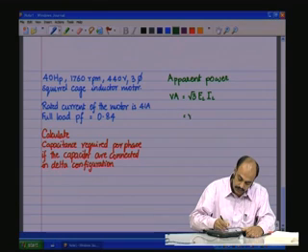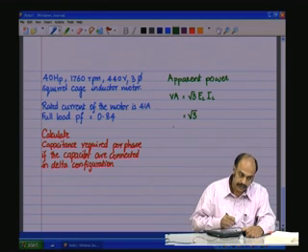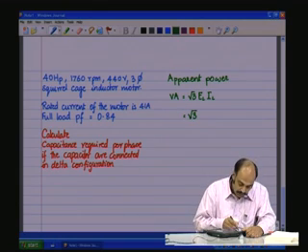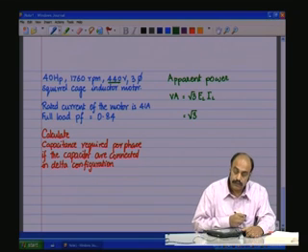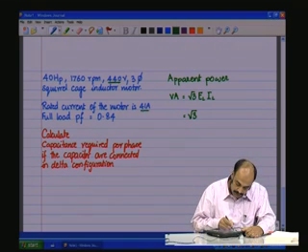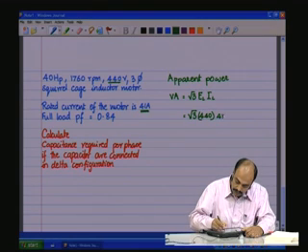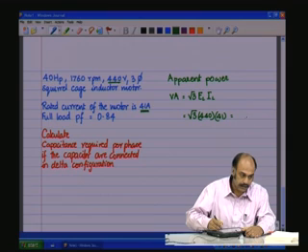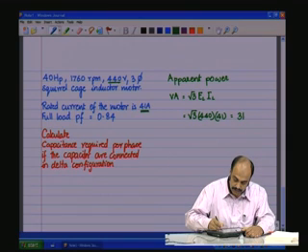The line voltage is 440 volts. The line current is 41 amps. The value is given here. So root 3 into 440 volts into 41 amps, and that is 31.2 kVA.